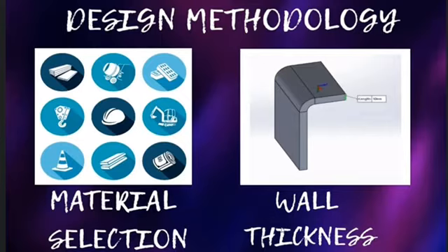Designing. Below are the factors which one needs to consider while modeling a sheet metal component. Wall thickness: while designing any geometry, it is always a good idea to maintain uniform wall thickness throughout the body. Geometry with more than one wall thickness requires sheets of different thicknesses, which requires reorientation and alignment of parts that consume time. Parts with different thicknesses will have different bend parameters, which may result in inaccuracy of the desired shape.